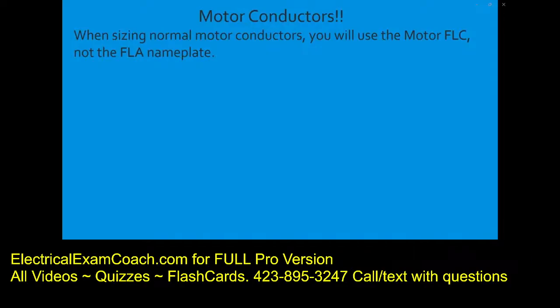Remember how we've learned previously that every piece of equipment has a nameplate, and it'll say things like what voltage the equipment is and what the amperage is. Well, on motors, they'll typically stamp an amperage, but that's the FLA. So when we're sizing normal motor conductors, we're actually going to use the FLC, and I'm getting ready to teach you how to find that value.